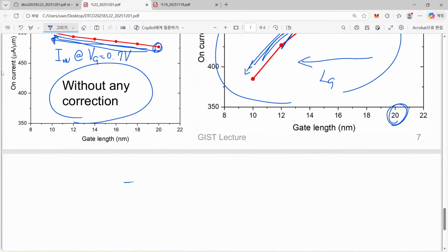here we have a FinFET, which is 7 nanometer, 32 and 32. Of course, it has a sub-fin and STI, but let's just say that you are now trying to simulate a 7, 32, 32, 7 gate all around transistor. Then, in terms of its effective width, maybe they are equivalent or quite close to equivalent. However, can you say they are equivalent in terms of layout?